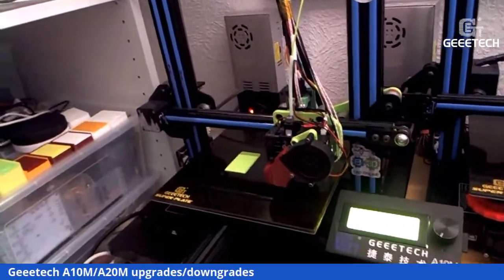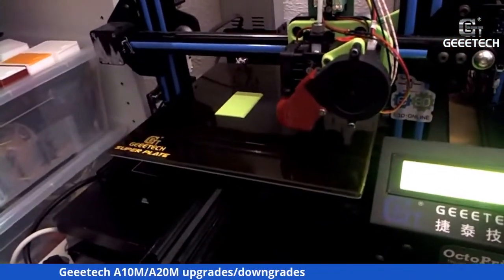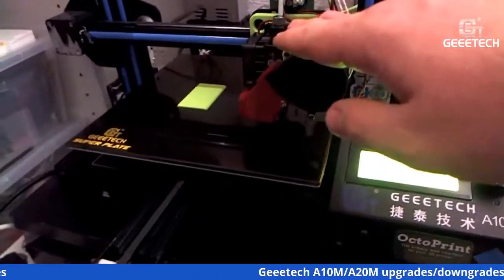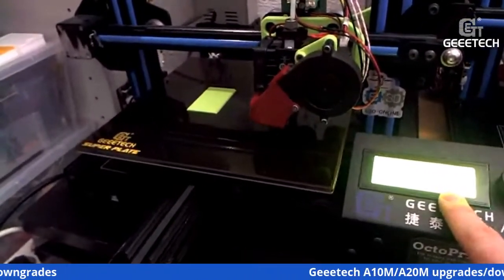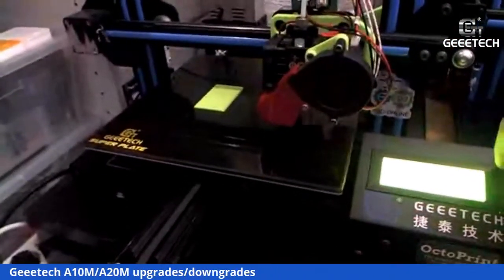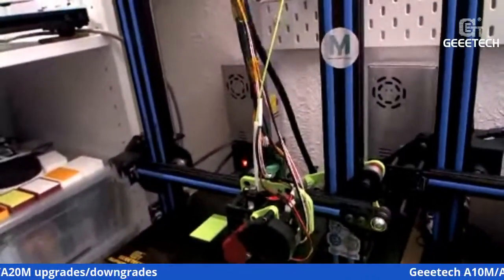Also a feature which is an advanced feature, baby stepping. You can enable this in the Marlin firmware, so you can live adjust with this knob the height of the nozzle. So if you didn't level the bed correctly, or it's too wide from the bed, you can still adjust the height after you started the print. So you don't need to stop the print and re-level the bed. You can do baby stepping from the knob here, and that re-levels the printing head to the bed by little baby steps. Okay, that was the A10M.